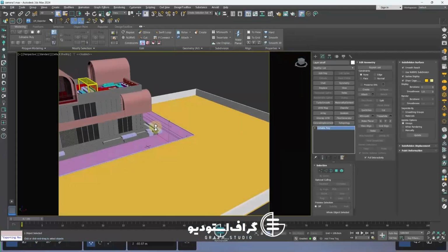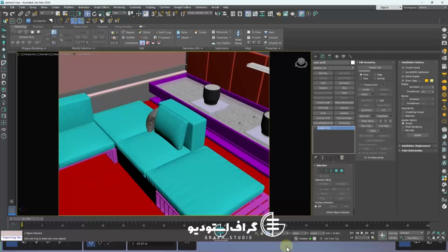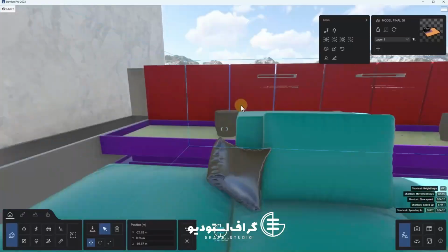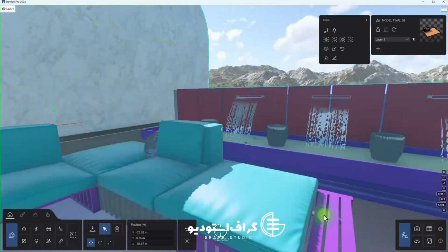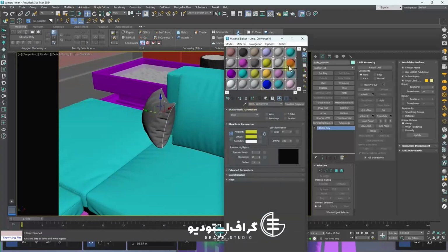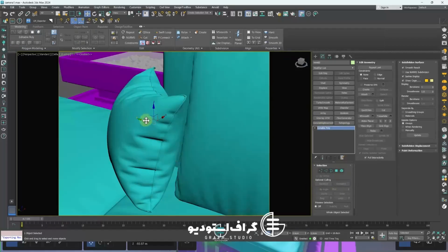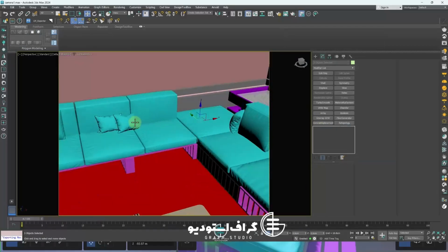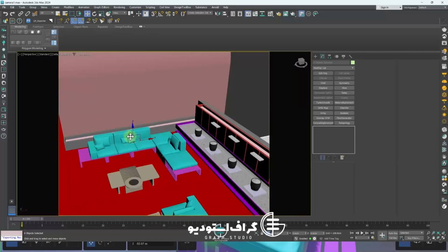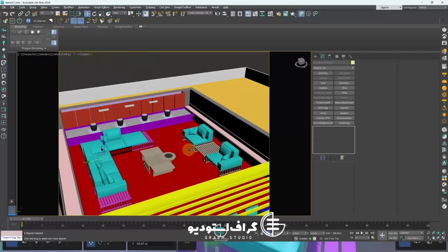The scene we received was full of grass here, or they had placed trees here to show the design concept. When I imported that, it became too heavy, so it was practically impossible to import. Therefore, I deleted all of them, and now it is enough to easily transfer this scene into Lumion and begin our work. Guys, you just need to select this. First, check that it's near the coordinate origin. Look, if I look from the top, I place it exactly on 0, 0 like this. Ctrl+I invert selection and delete.